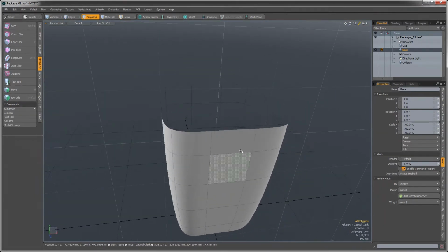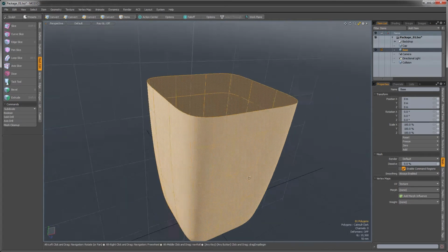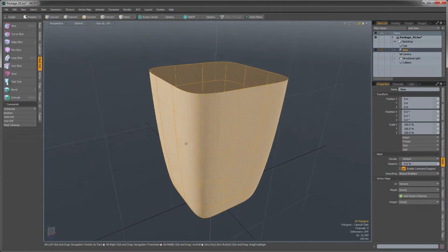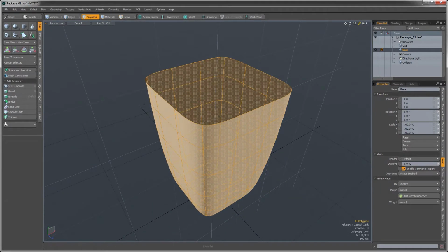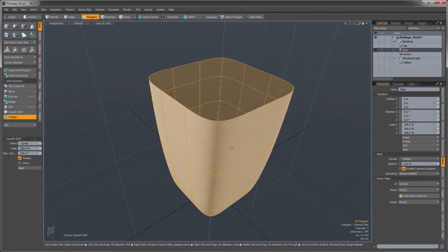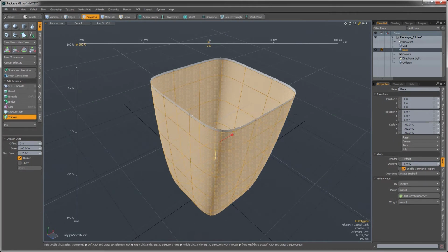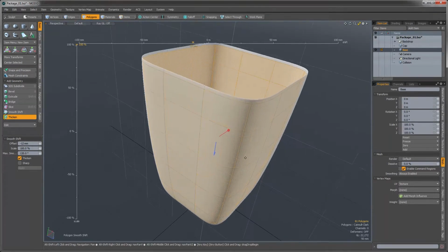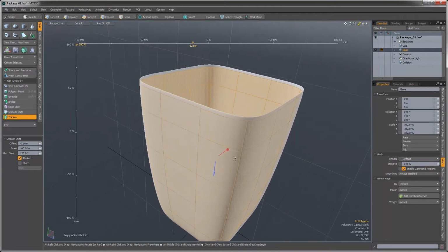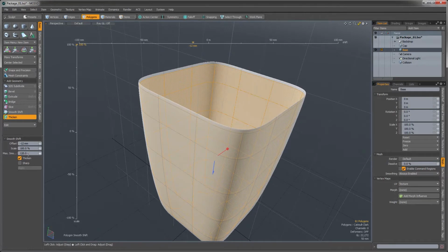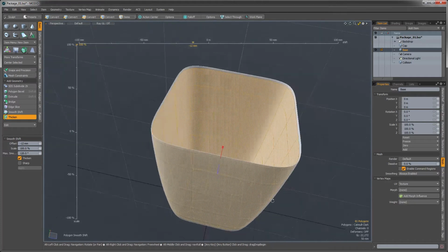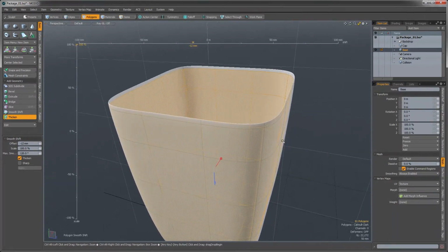So now what we want to do is thicken this so that we create sort of the inside and the outside thickness. So we're going to do that in Basic and just grab the Thicken tool. So we're going to click in here and we're going to drag that inward. So it's going to be negative 12 millimeters is how thick we want this. And you want to make sure that your scale is 100, and then just in case, I always increase the maximum smoothing really high, so I give it like 120 degrees. And for our purposes, that gives us the thickness of our packaging.